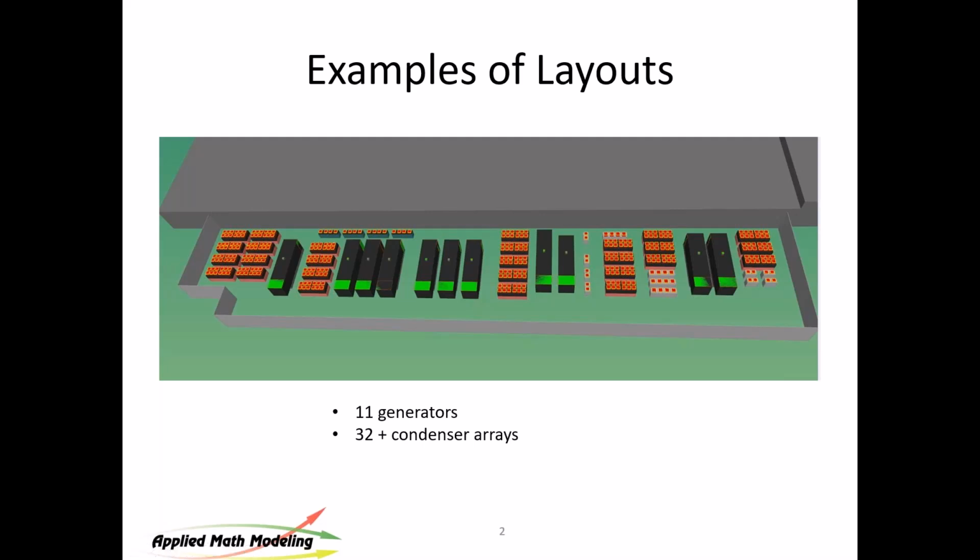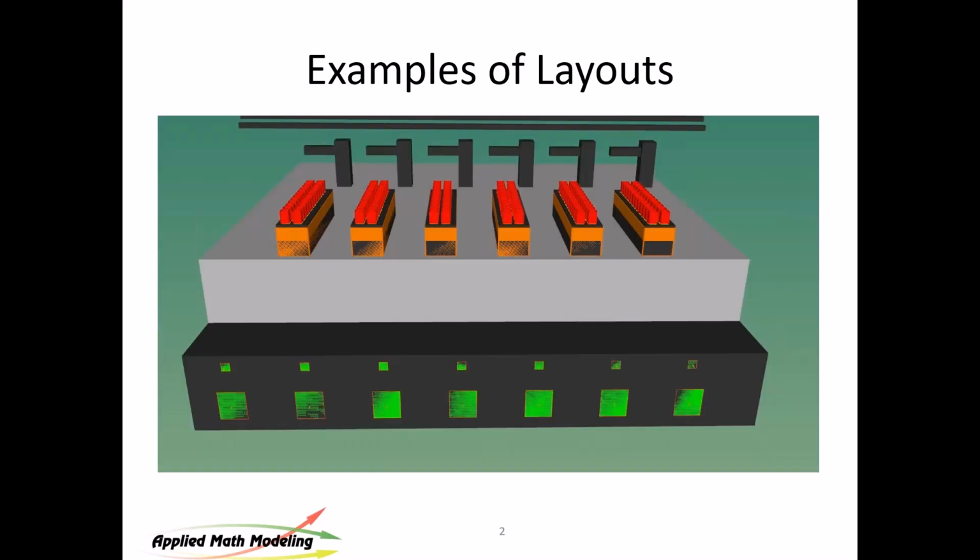I can stare at these and understand what the worst case condition might be, but that's experience. What you'll want to do most likely is experiment and run and get a feel for what that building looks like as a function of wind condition and wind velocity. It can be a little tricky. Sometimes low velocity winds are worse than high velocity winds because they create some pressure gradients that may not be there if it blows a little harder.